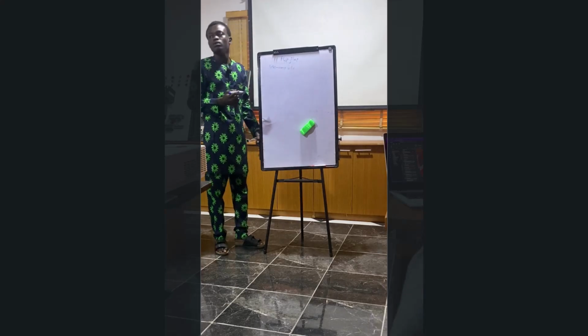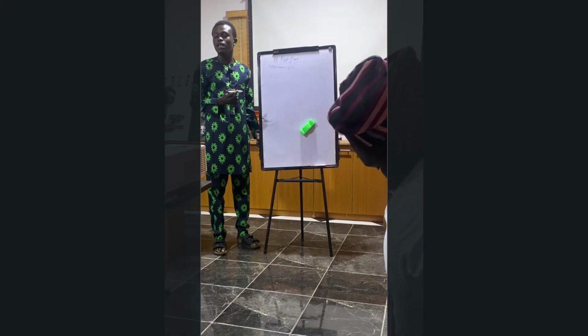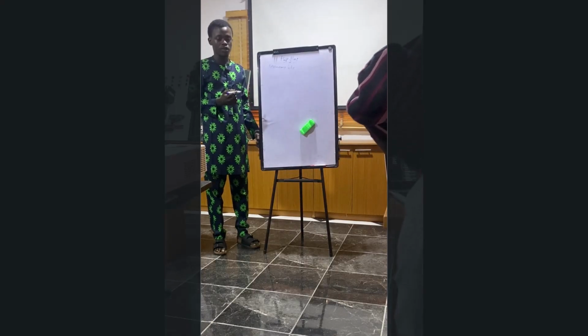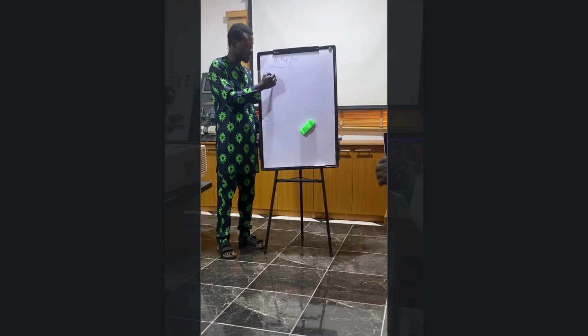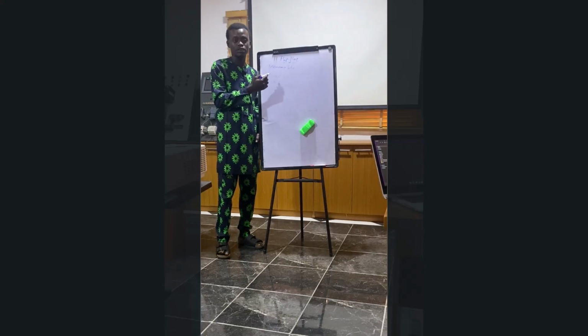Since last week in our programming, we have been using addresses such as I0.0, Q2.0. Basically, we have been using the process image input and the process image output. We have been using the input addresses and the output addresses for programming. But you might be in a situation where you want to have a kind of placeholder memory.